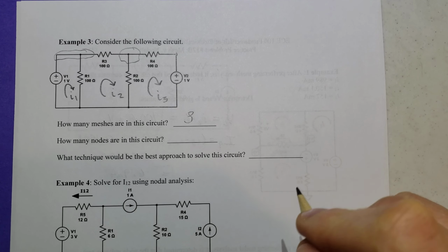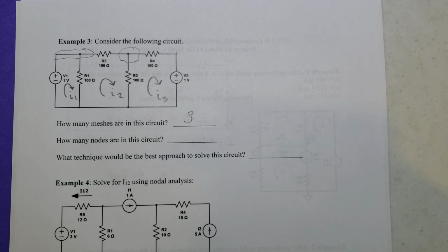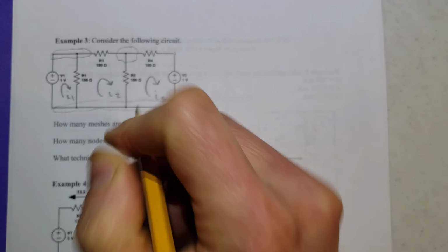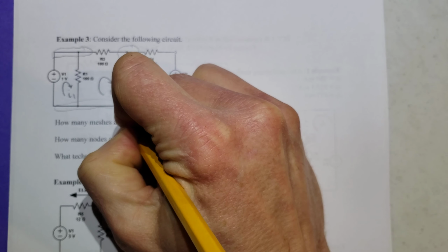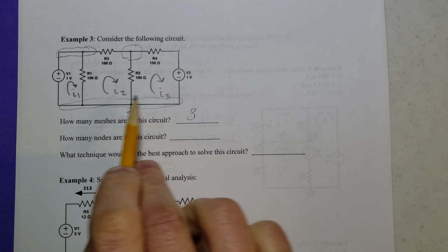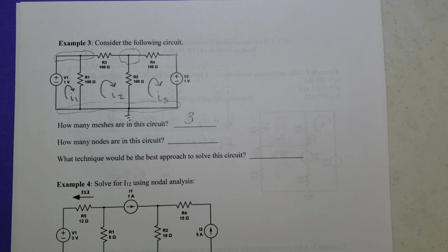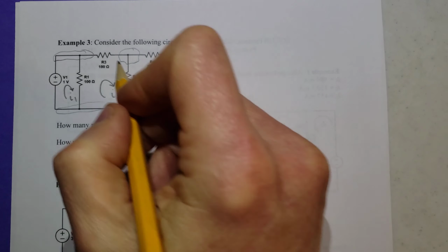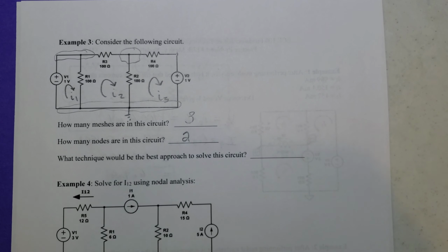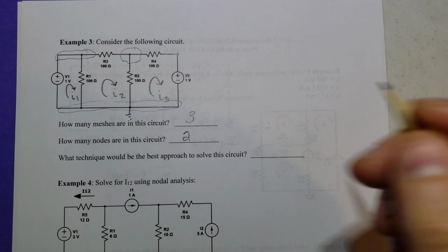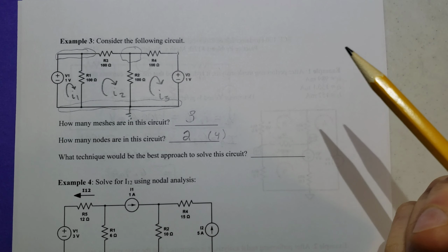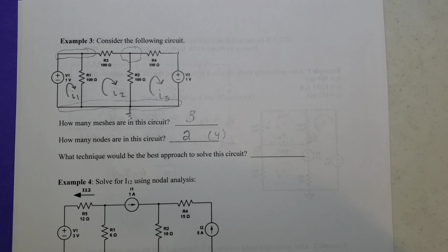All right, so we're all ready to put down 2 here, but you know what? We've missed another one because this is a node here, but the first step is always to pick your reference node. And so we would be grounding that out. So that's the 0 node. It wouldn't come into play. Well, it depends on how you count them, but the idea is we'd want to know how many equations there would be. So here there'd be 2 equations worth of nodes in that, but technically there's 4. This is the answer we'd be caring about, because we want to know how many equations there would be.